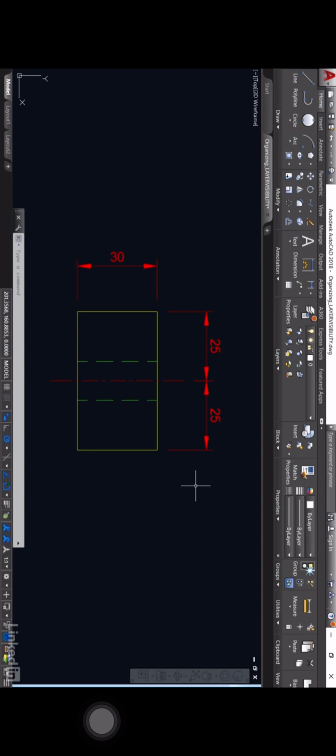Now there's one more setting, and it's in your layer properties. If I go here like so, you'll notice there's a thing called transparency here, and it changes the transparency for the entire drawing with these layers. So if I go to the object layer and click here, I can actually change the transparency value of the layer. So when it's on top of something else, it's actually transparent. Right now, 0 means that it's not transparent. But if I change that to, say, 90, it'll be transparent to a point whereby there's a little bit of transparency there and you can see objects through it. I'm going to set that back to 0 now, just to be on the safe side, and OK it.